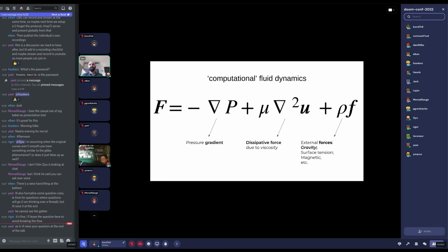And this makes perfect sense if you think of, like, you squeeze something, then it shoots out. You put lots of pressure on it and it will go towards where there isn't pressure. Or when you open your tap, you're creating pressure where the water comes in, and outside there is just atmospheric pressure, so less pressure. And this is the most fundamental thing in understanding how fluids move. It follows the pressure gradient.